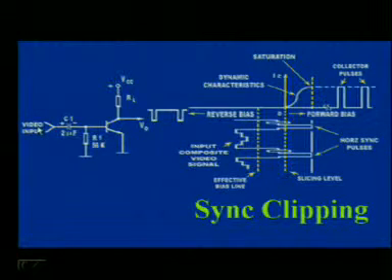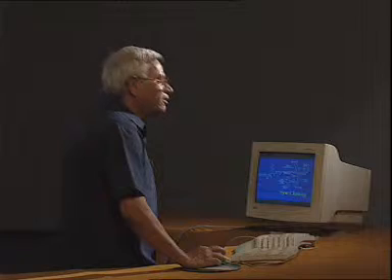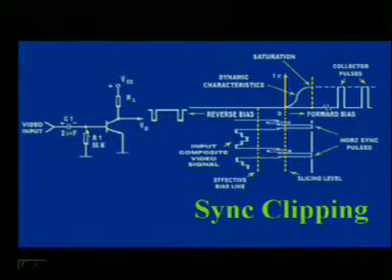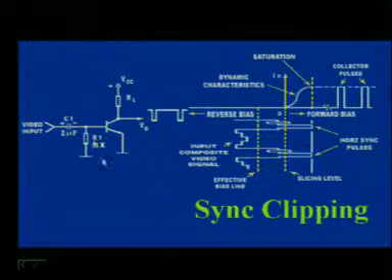Composite video signal enters this transistor and syncs are separated. But how are these syncs separated? There should be some region. This transistor comes into conduction only when the amplitude of the sync pulses reaches 75% of the video signal, and the remaining 25% of the video signal brings this transistor into conduction, with the result that the base of this transistor is forward biased with the help of sync pulses and goes into conduction, and syncs are separated.